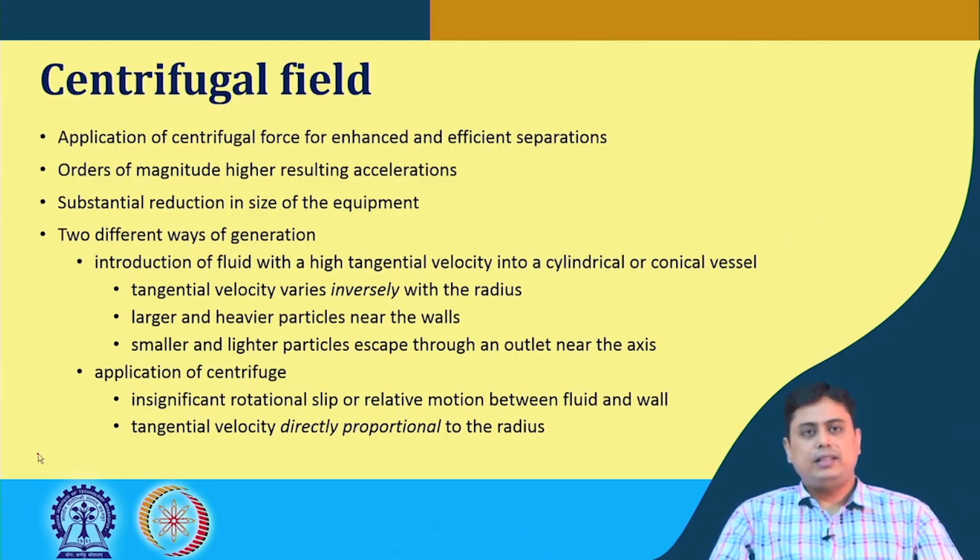Application of centrifugal force enhances the separation by orders of magnitude compared to gravitational settling. It results in very high accelerations in the field that lead to efficient and enhanced separation of particles. It is not only separation; in drying, in breaking colloidal particles, or destabilizing an emulsion, such applications of the centrifugal field are of immense importance.